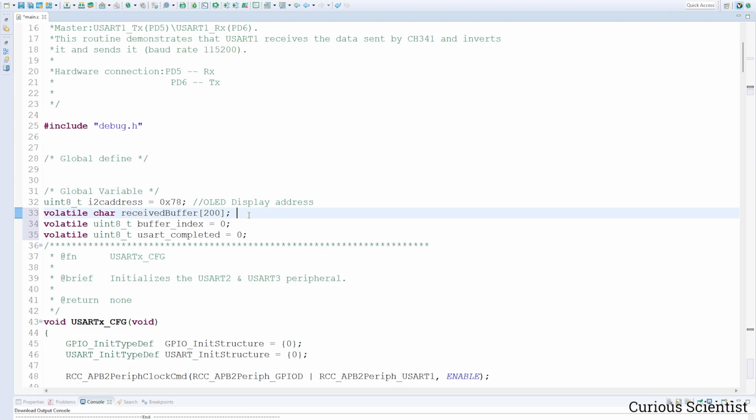Every character is just 5 pixels wide, and we always print a dummy pixel after the character that we print. So actually one character is 6 pixels wide, and our display is 72 pixels wide. And that's very lucky, because 72 can be divided by 6, which is 12. So each line can accommodate 12 characters, and we have 5 lines.